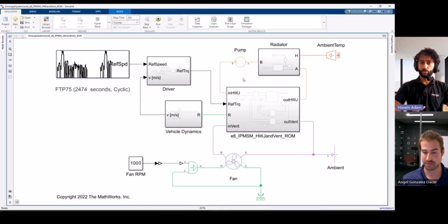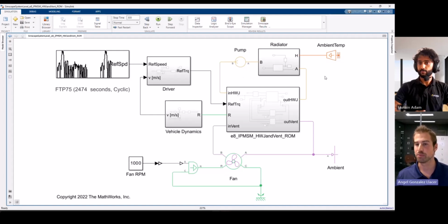So in this case, it's not just the fixed analysis that you might do in MotorCAD with a fixed flow rate and temperature, but here you're incorporating the real physics of the radiator, the fan, and I guess you said these results would generally be shared with other team members and be used for their design as well. That's right. Yeah, you could share models and have people replace components with their own models so that they can evaluate how their iterations in design have impacts on the other team's requirements and performance. So it's a great way to collaborate.